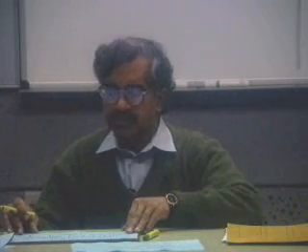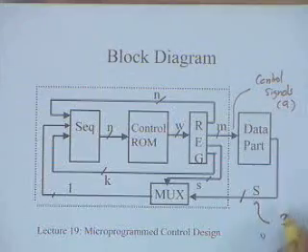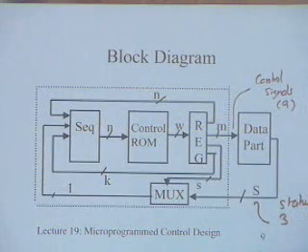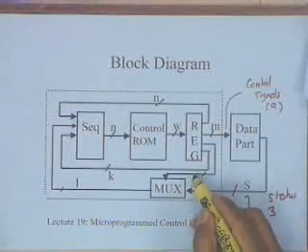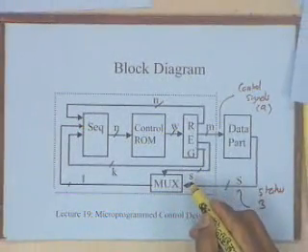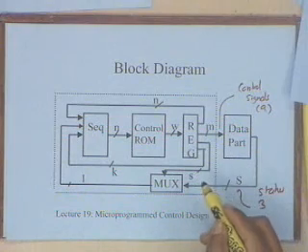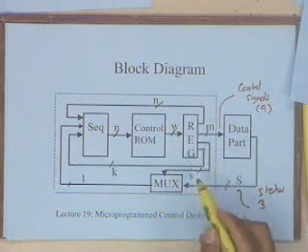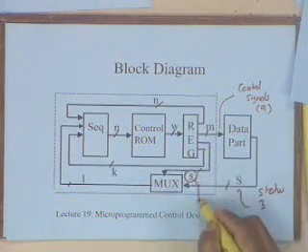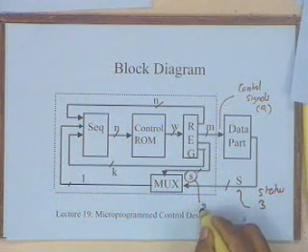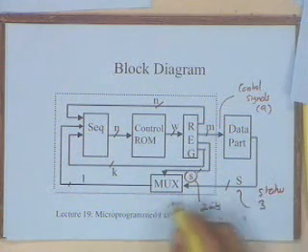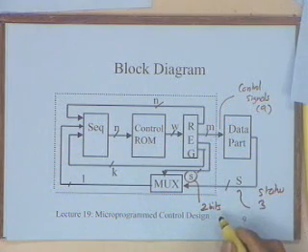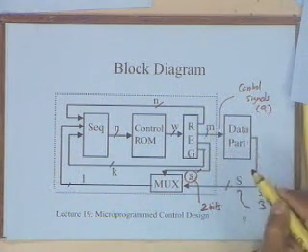So I have these control signals, 9, and I have these status signals which are 3 for this particular case. I can decide on the size of S. What will be the size of S? I will at least require 2 bits to select among the 3 status signals. This will be the size of S. Size of M is already 9.